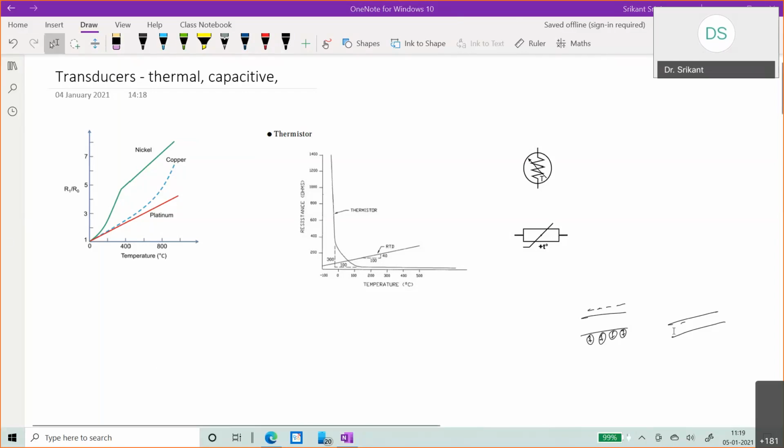So what happens in the case of a metal, where there are already a lot of carriers, there are already a huge number of electrons, is that by increasing the temperature, the slight increase in the number of electrons is not too much. But on the other hand, the existing electrons, which already contribute to high conductivity, experience carrier collision, and due to carrier collision, the resistance increases.